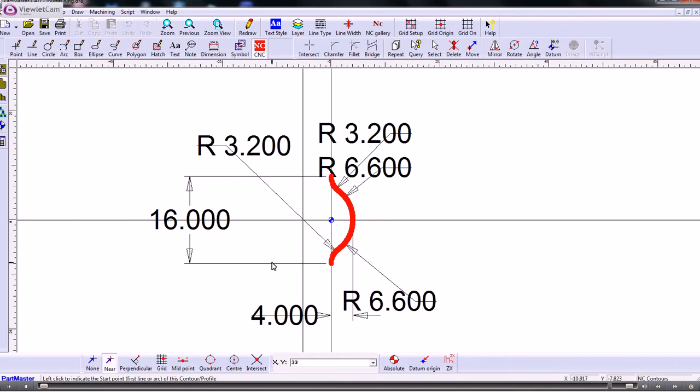Okay, in this video we'll try and show you how we do this bump ring. So just reading the PDF file that was sent through, I've just created a little bit of geometry. I assume that this is going to be cut on a rotary axis mounted along the x-axis, which would make that the a-axis. So I've produced just that one part, which is the 16mm pitch from one to the next, and I've made my datum position the center there, and that's just produced an open contour.